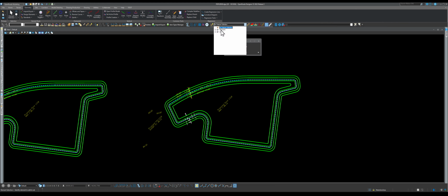So I'm going to select a feature right now because I want y'all to get exposed to this, because most people don't know. This is where FDOT has the ponds feature definition hidden. It's under linear, then roadway, and then where's the ponds, and there's the ponds. Here we go. And then they have pond bottom, pond control, pond peak, and pond slope break. So you can start either from the top or the bottom, right? So right now, I'm just going to start from the pond bottom.